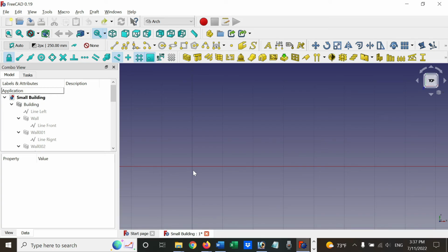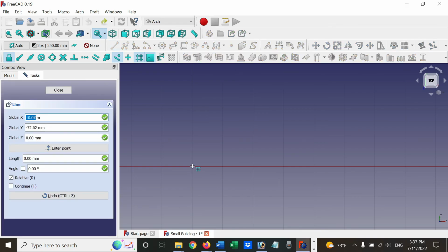So why is it important to know how to create a line using the coordinate grid? Let's say your line is not 3 or 2 meters, it's 2.5 meters. Let's try. Snap here, 2.5 does not snap. It snaps only on 2 or 3.